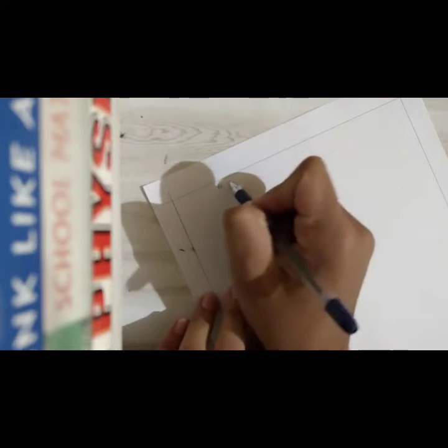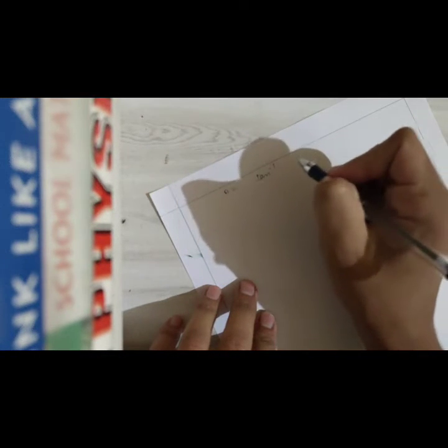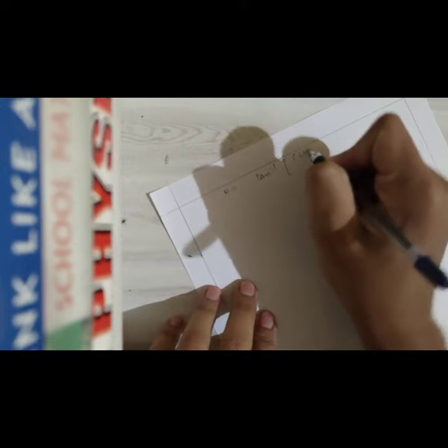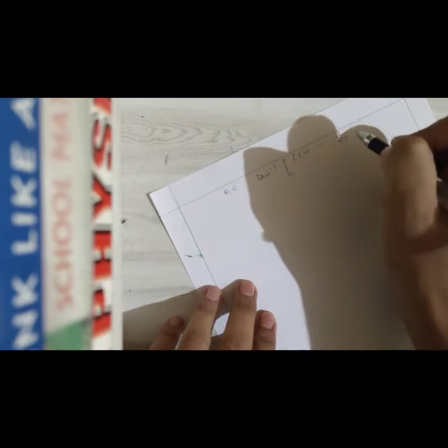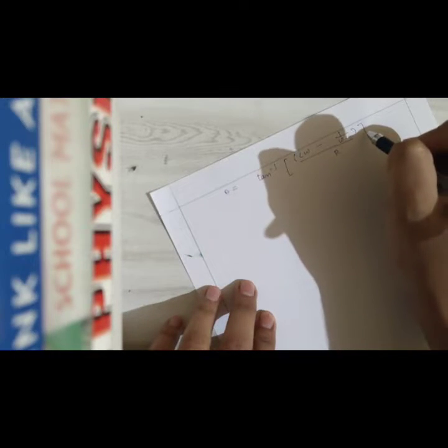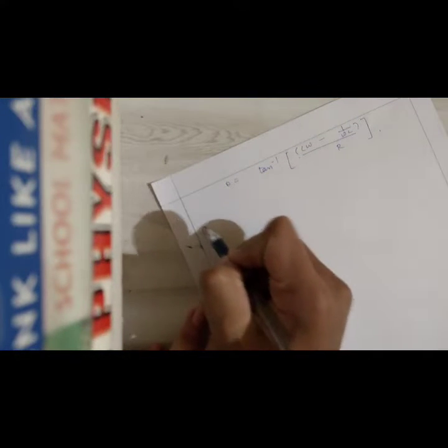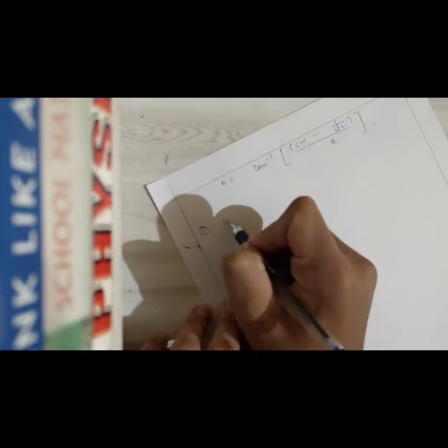At the end of our calculation, when we find the phase angle, that is our theta equals tan inverse of (L omega minus 1 by omega C) over R, there arise three cases in front of us. First one is our case 1.